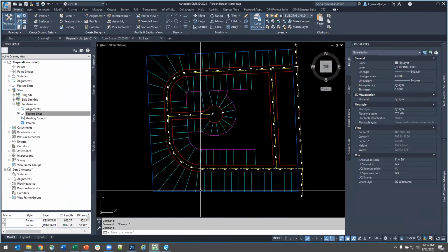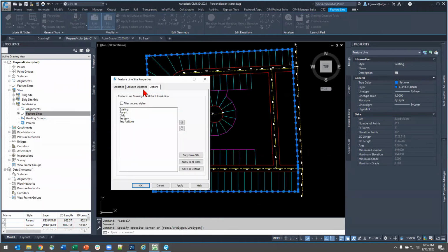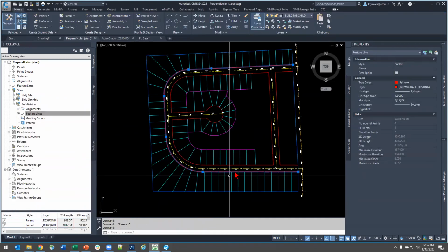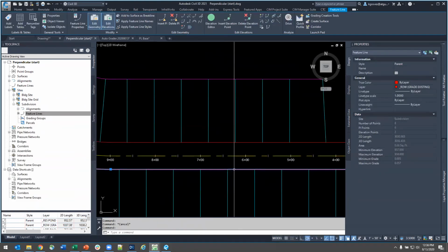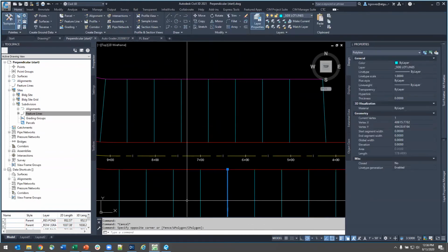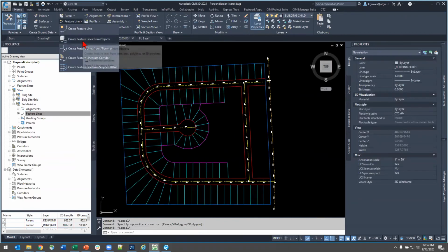Mainly, the fact that at the edge of our subdivision, this is our elevation from our existing. So eventually we do have to tie back into our existing. My existing feature line style is at the top of this hierarchy. So whenever my new lot lines are going to cross it, where they overlap, they're going to take on that elevation. Also, my parent style is at a higher hierarchy than my side lot line is, or rather that my child feature line is.